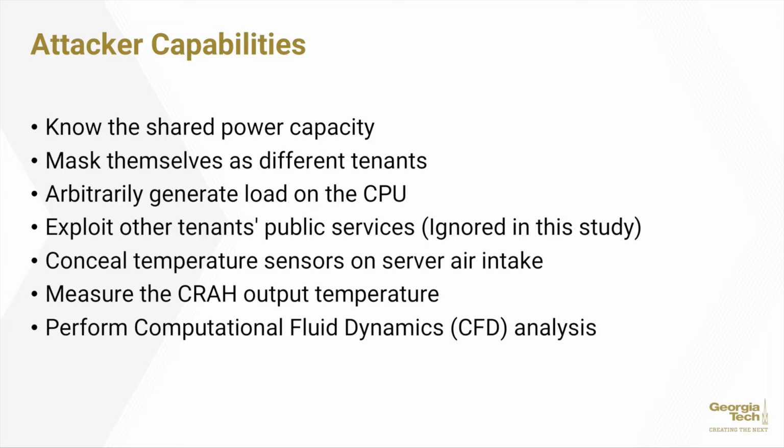Some things that we need to note here: you can actually walk the data center and get an idea of the layout. So where are these CRAHs located? Where are the servers located? How are they aligned? What are the approximate distances and approximately how many servers exist in this data center? Approximations are fine. And we're going to plug this into something like AutoCAD CFD in this case and create a fluid model for the heat flow throughout the data center.